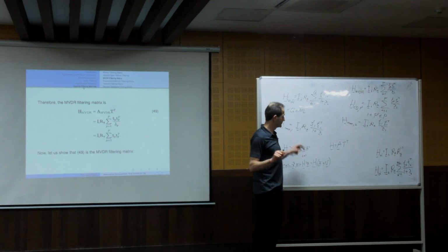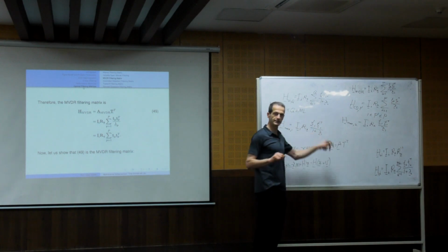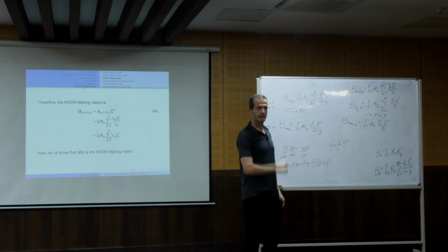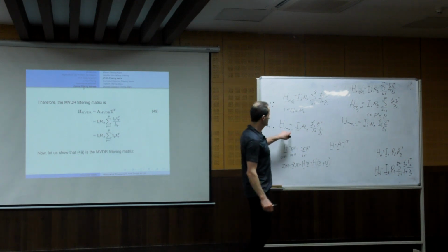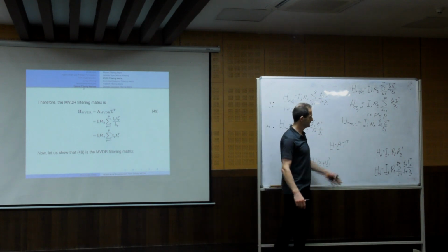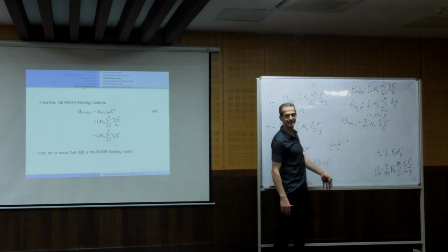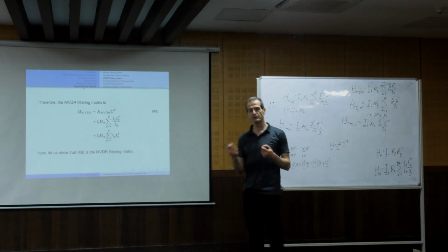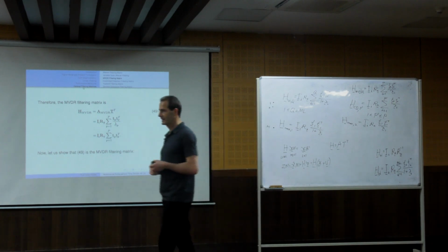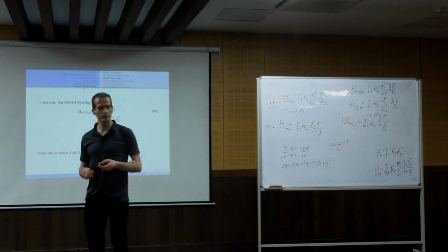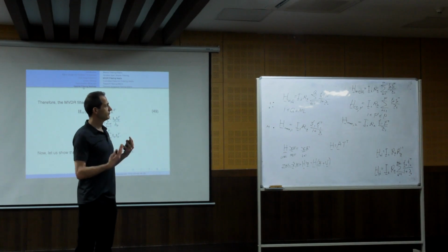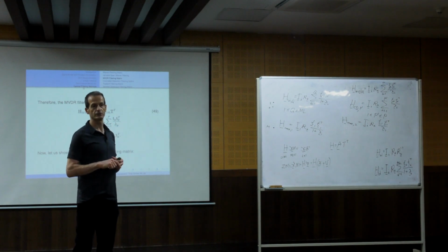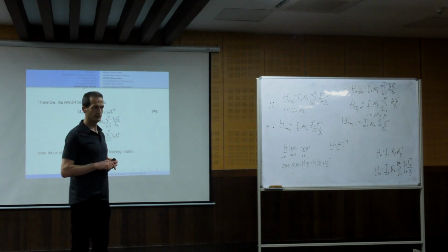Okay? So we have here different expressions out of the infinite number of filtering matrices that obtain the maximum SNR. We have specific solutions that we got immediately from these expressions. You see the beauty of these derivations, and it allows us to find more ways to control between signal distortion and noise reduction.